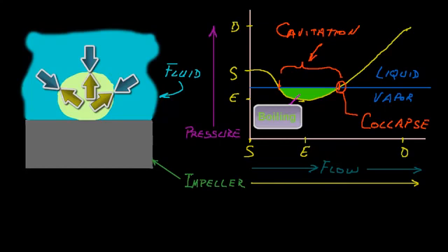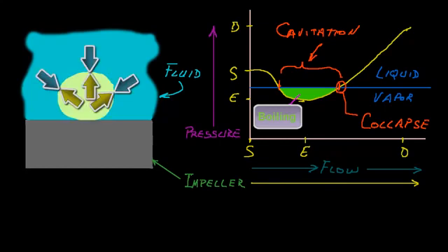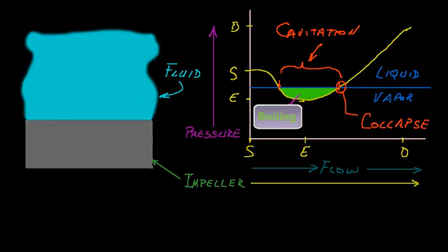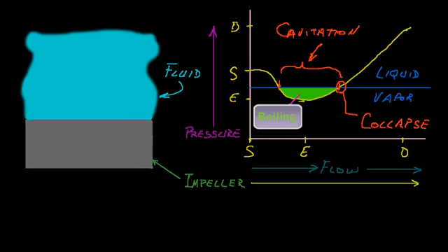It is important to remember that this process is not a one-time isolated event. Over time, the continual pounding of the fluid impact destroys the surface material at that location, and the resulting pitting in the surface of the part is known as cavitation damage.